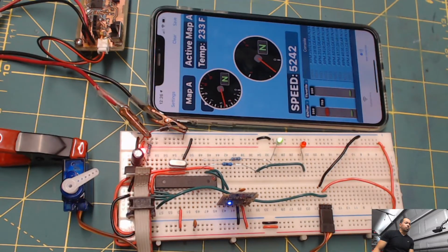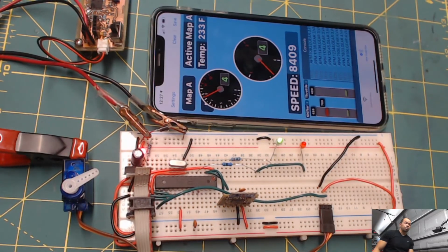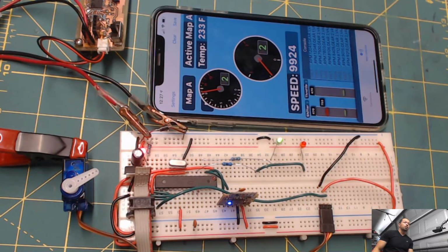We get the field and the message, a pointer to the field and the message. Then we check to see what type of message we got. Did we get green on? We did. Turn the green LED on, send the command back to the label. Is it red? Turn the red on, send the command back to the label saying red. For servo, if we get a servo, then we just get the value and assign it to the output compare register A, which is pin B1, which is the one where the servo is connected, and it changes accordingly depending on the value you set here.